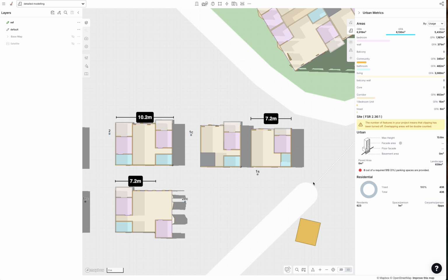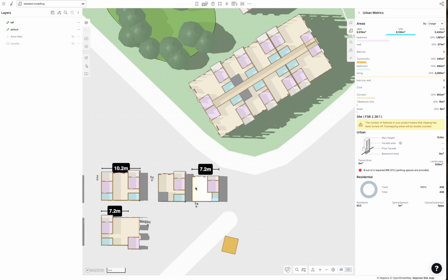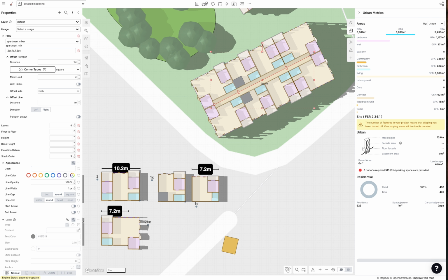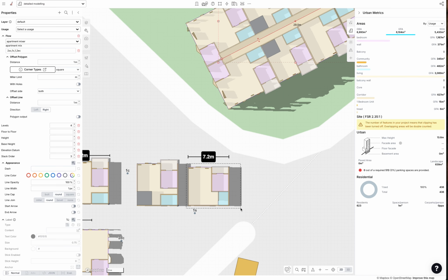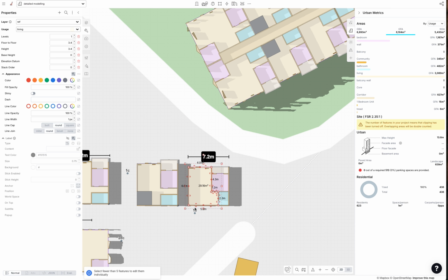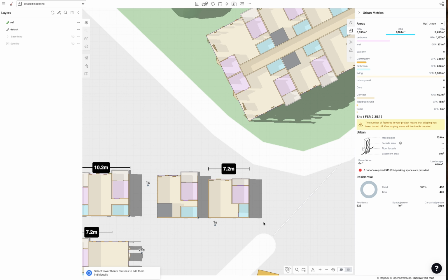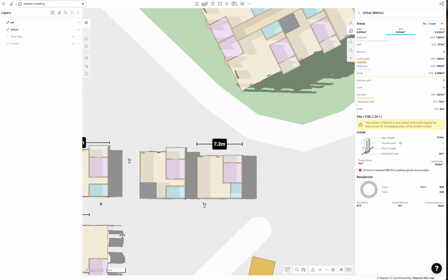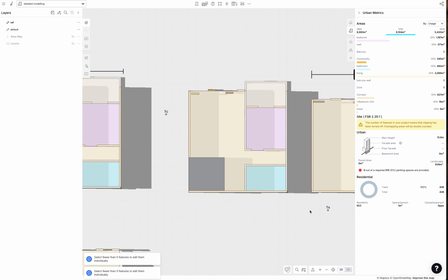There we go. Right. And you can see in the next video how you apply this apartment to this flow, but why don't I just do it now? So the thing you need, we're going to turn this into a group. And so for us to make that work is we need to group it. But for us to be able to instance the group accurately, we need an insert point. And you can see my convention is the insert points go on the right-hand side there.